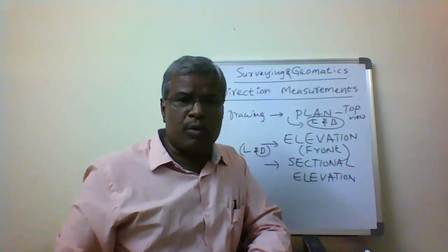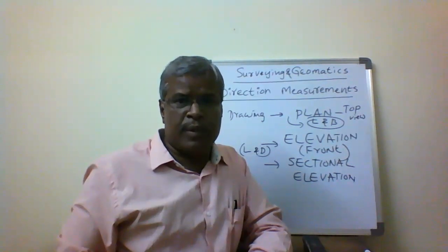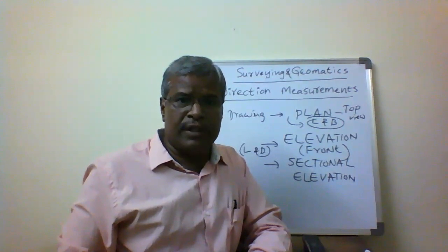From that direction I am going to be calculating the bearings. From the bearings, we are able to get the included angles. So the angular measurements, we are going to be getting as indirect measurements by using the compass.